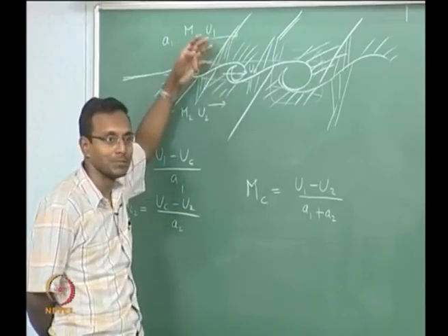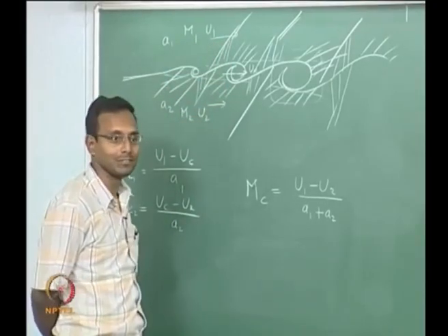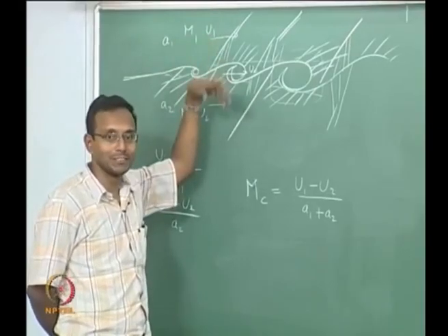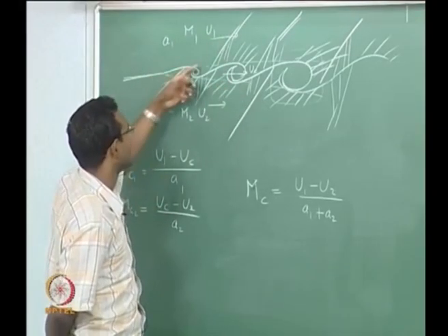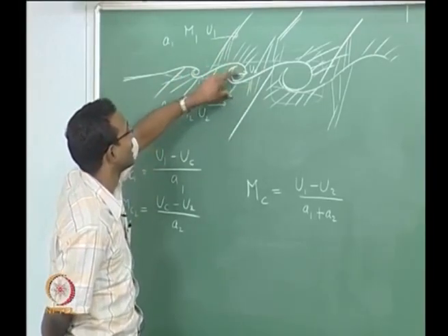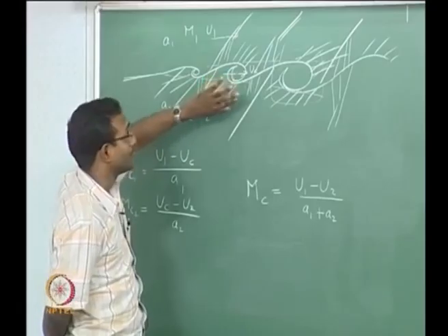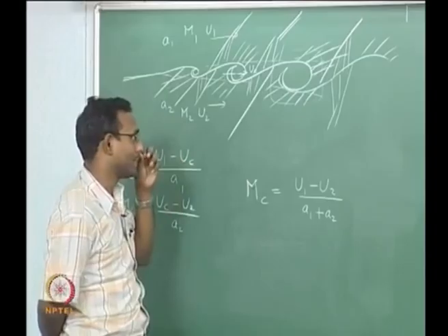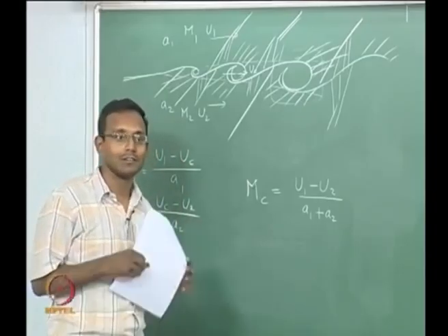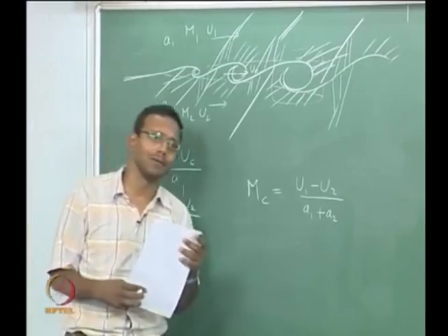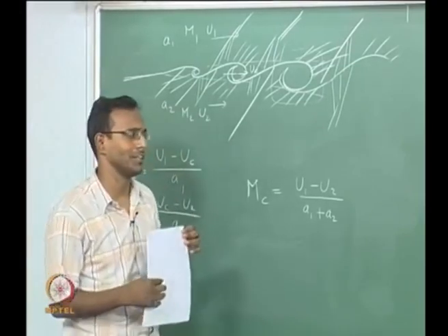This is what they study as the mixing layer in supersonic flows. This is going to take the bottom fluid up and the top fluid down and mix them. As it is, you can see that it is doing that by taking this fluid down into here, and this fluid has gone into that gap. But it is much more if I go for higher convective Mach numbers, where it will go to three dimensional structures. There are special research papers where they do this, and the most recent paper I have seen was from 2003.